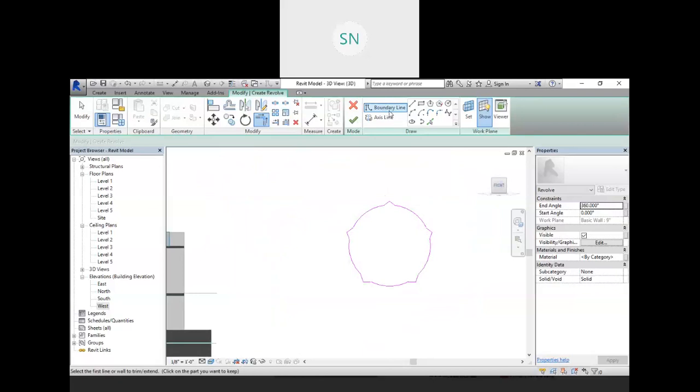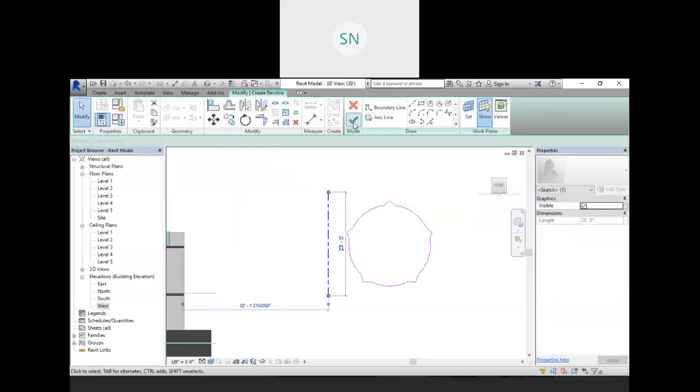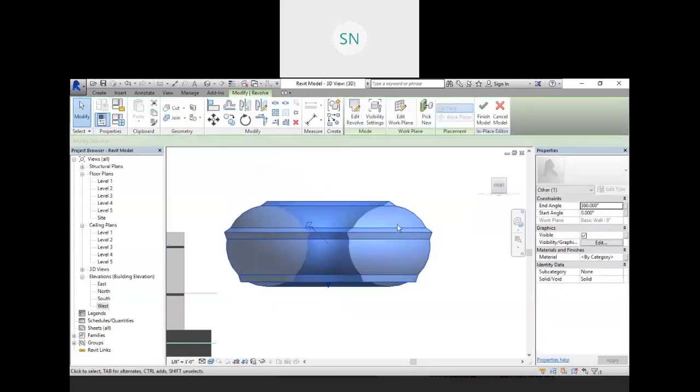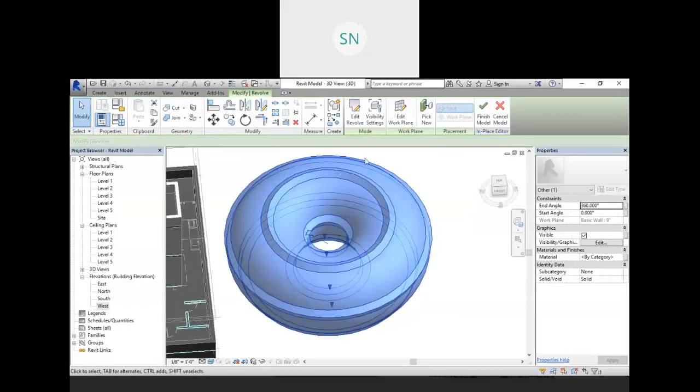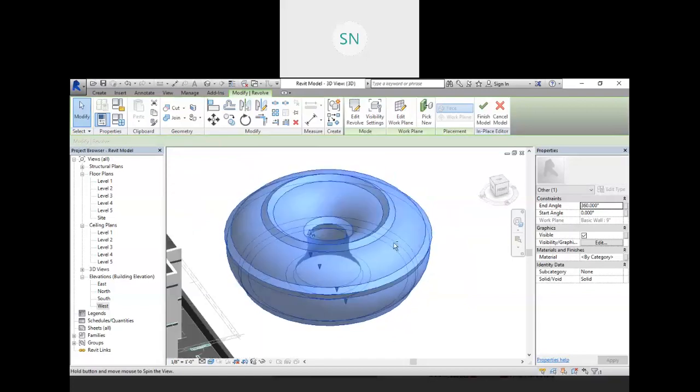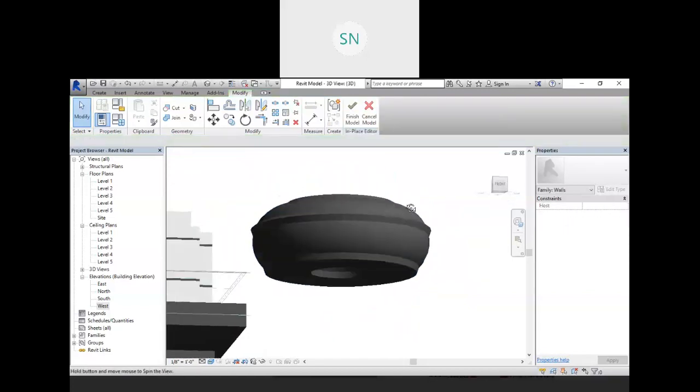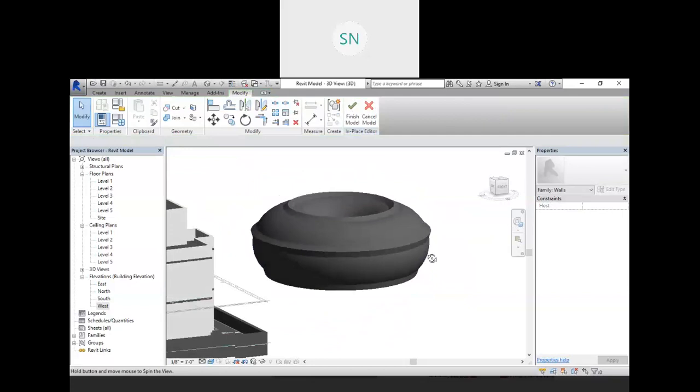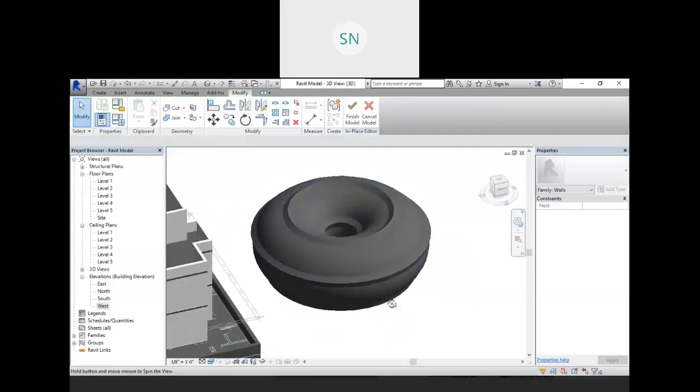And now the revolve axis. So here I am creating a revolve axis. This is my axis, and click on Finish, and you will get a revolved geometry. See, our object is actually going to revolve around that axis, right? So this is our revolve geometry. I hope you get the idea now how this revolve feature works. Is it clear now?